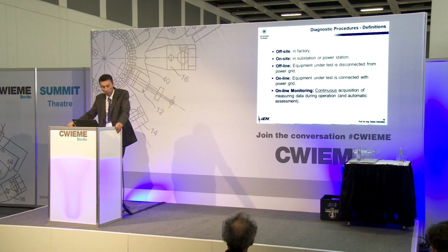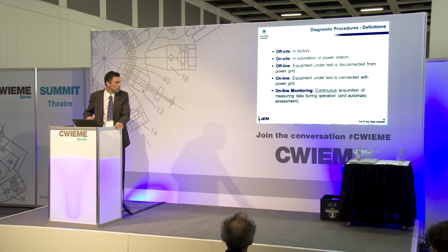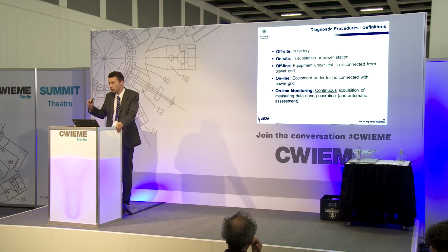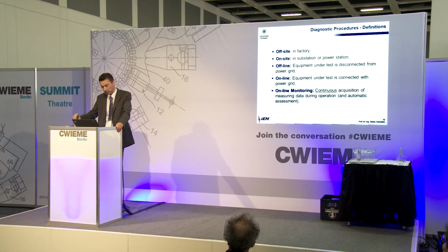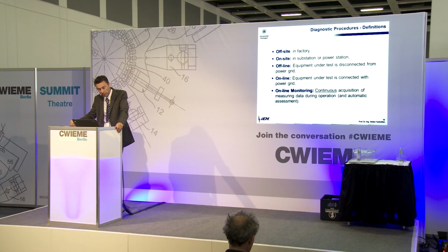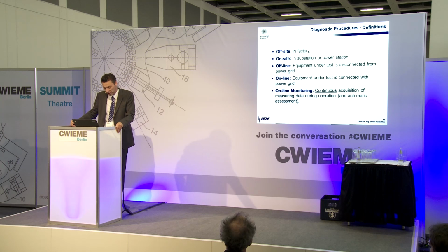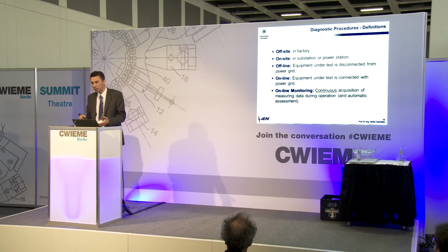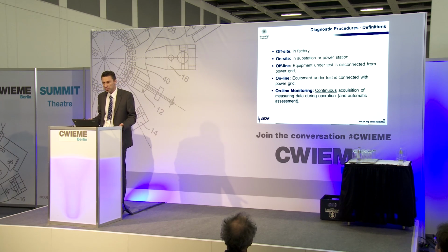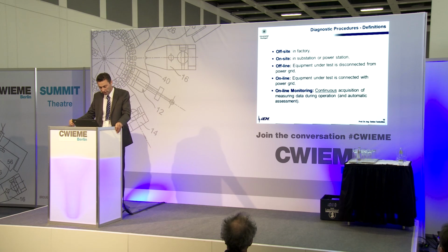The third is online monitoring. So we have to distinguish here between an online measurement, which is a measurement done just on one day, so a single event, and online monitoring, which means you have a continuous acquisition of measuring data during the operation, and probably also automatic assessment of the data. So this goes one step beyond the normal online diagnostics, where you measure and then you look at the measuring data and you interpret these data by specialized personnel.